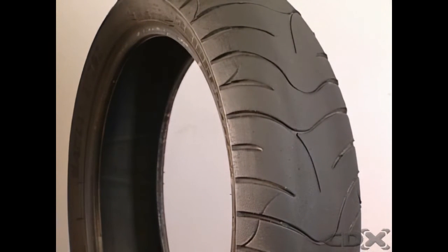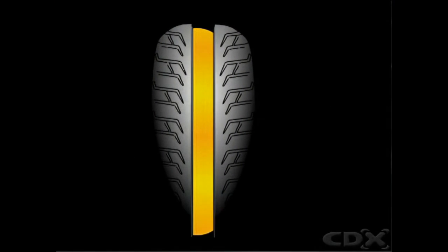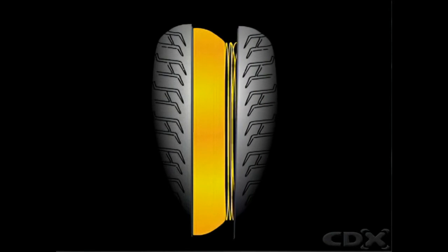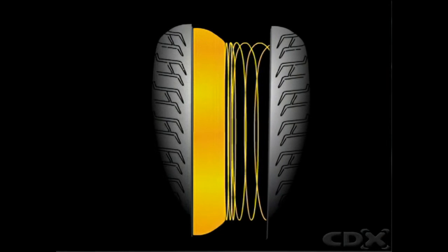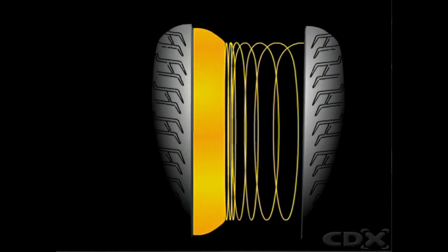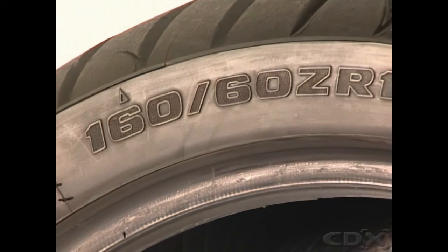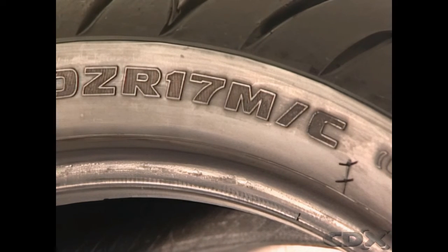Some tires with particular applications have mono-spiral belt, or MSB, incorporated into their design. With this technology, a single continuous thread of steel is wrapped around the circumference of the tire, eliminating overlapping belts, seams, and joints. A mono-spiral belt tire is lighter than a tire with conventional multi-cross belt construction. It has more stability since it minimizes heat generation inside the tire and gives high shock absorption.